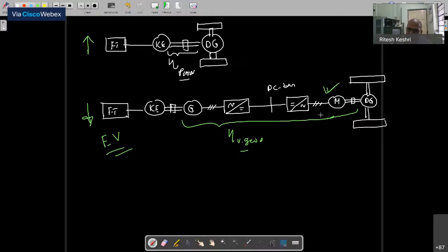You can see there are other possibilities also. Suppose that you want to have electric braking, it is possible. It is an electric motor, you can definitely do it. Suppose that regeneration is taking place, you can definitely recover the energy. But the important thing is that you cannot send it back to this side, so you have to use some arrangement. Maybe you will be using onboard storage, or maybe some ultra capacitor system. So different possibilities are definitely there.